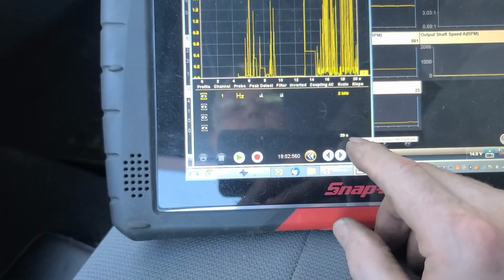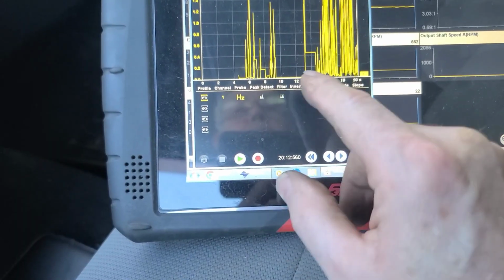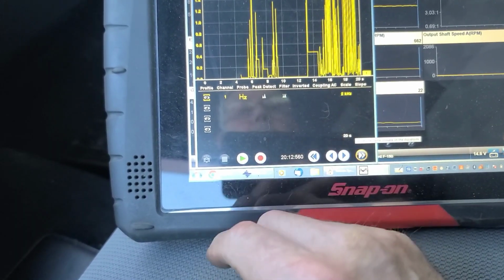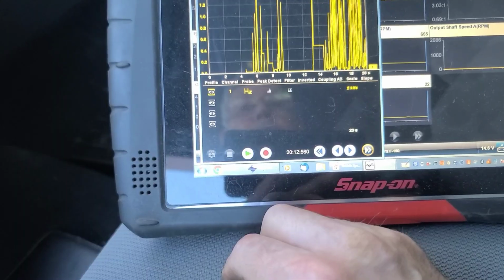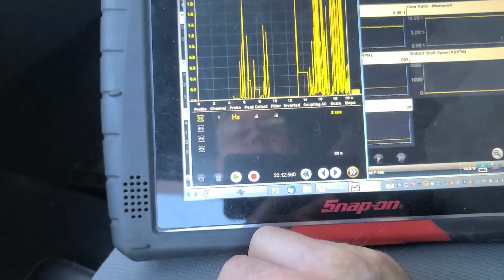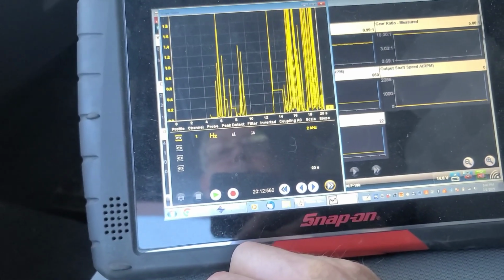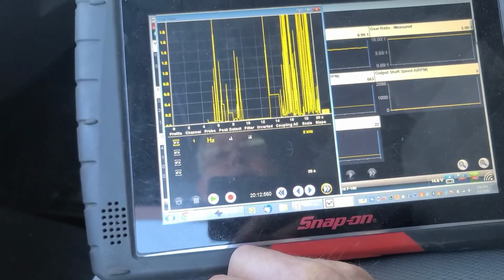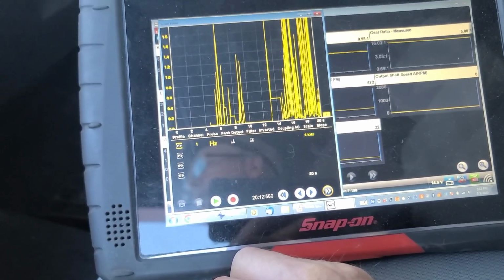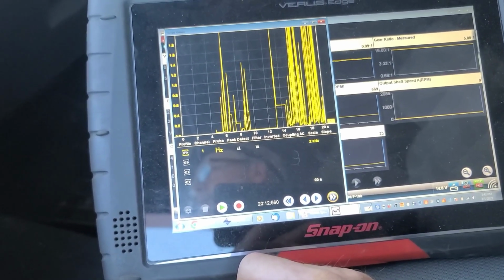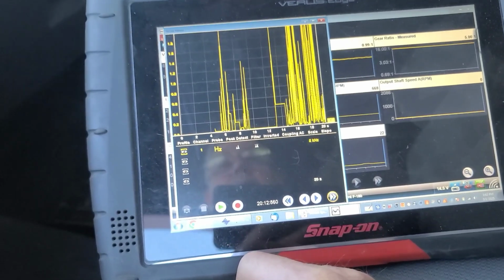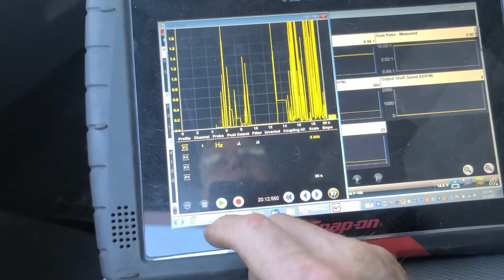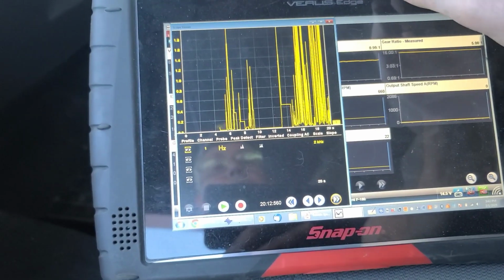So it lasted for about 10 seconds, or 20 seconds. The screen is 20 seconds here. Interesting, because I was concerned maybe it had a bad diode in the alternator and a possible RFI signal from the ignition coils, but the truck didn't misfire at all. It didn't run rough at all. Now, I think that Hall effect sensor is failing.